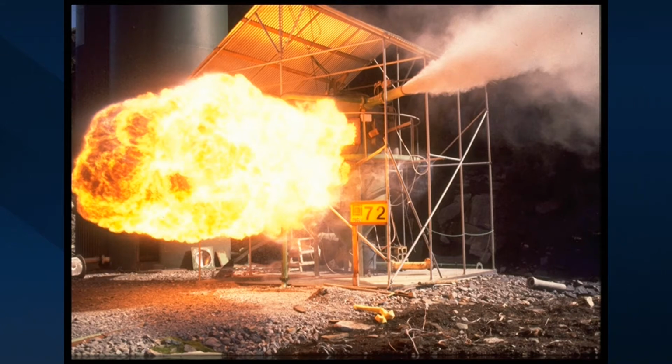In the first experiments, where we didn't stop the flow immediately, we burned all the filter bags, obviously, and we melted part of the roof that you have above there. And when we changed this and stopped the flow immediately, or had a kind of explosion isolation where a float valve was closed very quickly, we could do 8 to 10 explosion experiments with real filter bags before we had a number of holes and had to exchange a few bags.